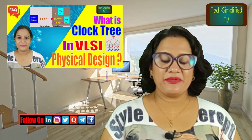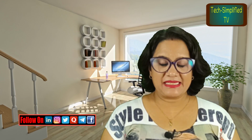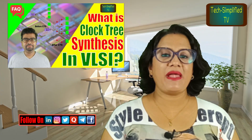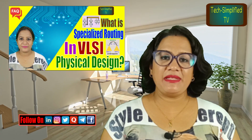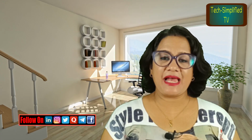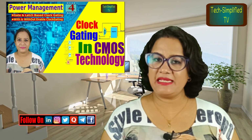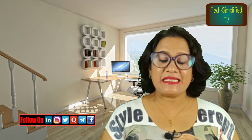So we will start with the foundation of clock network design in VLSI. Next, we will move to clock tree synthesis. We will try to understand different important parameters like delay, jitter, slew, and latency. Next, we will explore the advanced routing technique. From there, we will dive into clock gating. Clock gating is one of the most important power-saving techniques in VLSI design. We will try to understand different types of clock gating techniques.